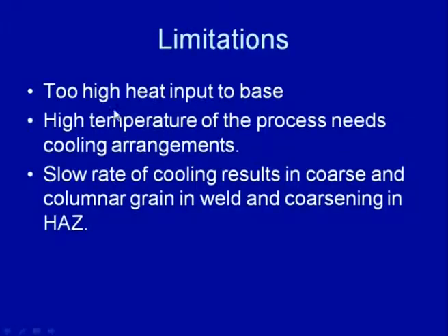frequently the joints made using the electroslag welding process are subjected to the normalizing operation, so that grain refinement in the heat affected zone can be done, so that the properties of the weld material and the heat affected zone can be improved. Further, the high temperature process needs a cooling arrangement. Proper cooling of the copper shoes is done, so that any melting of the copper shoes can be avoided because of the high temperature experienced by them.